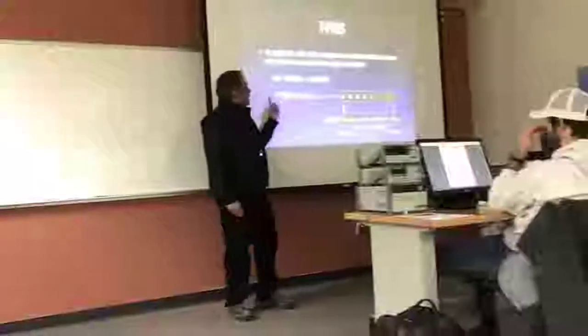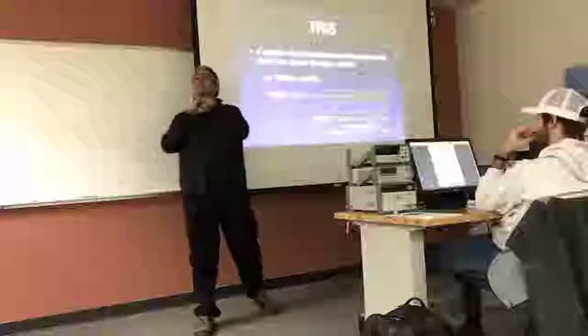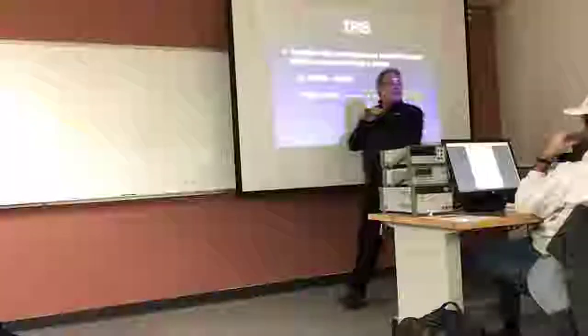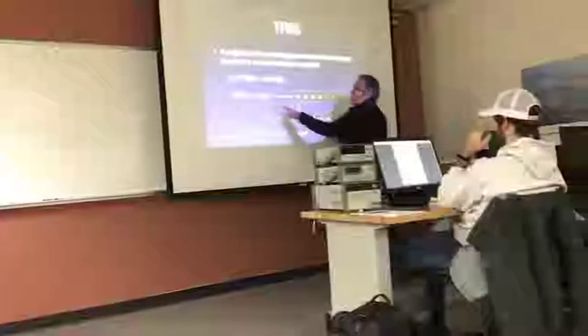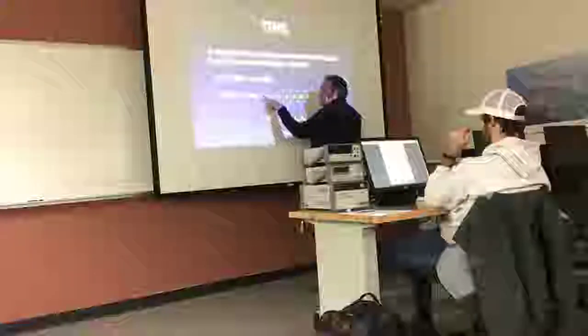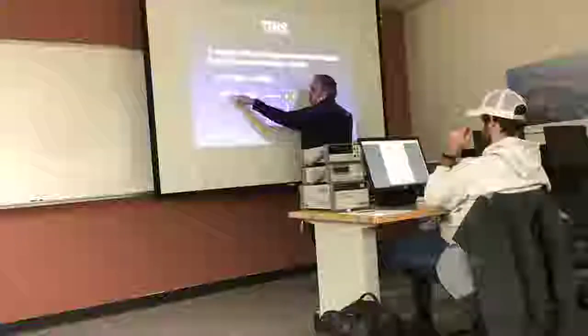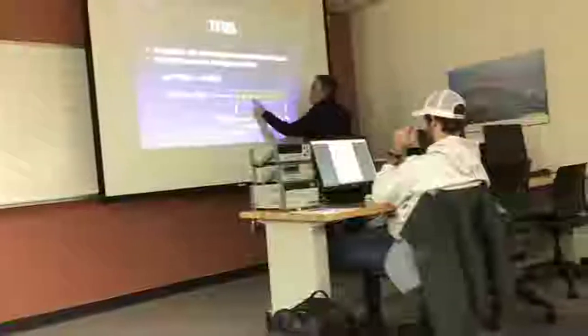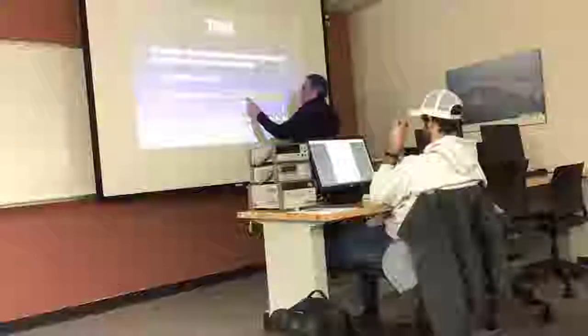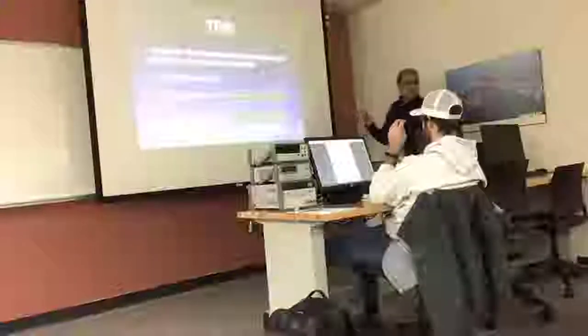So notice the direction of the arrows. When you're working with a tri-state device, software initiates the behavior. So if you notice, you start with the software. When I execute this instruction, I am depositing the hexadecimal number 1, a literal constant, into this location, which is going to force this to happen. I'm going to get 0, 0, 0, 0, and then the 1, and now you have 0, 0, 0, 1. That's what the software is doing.